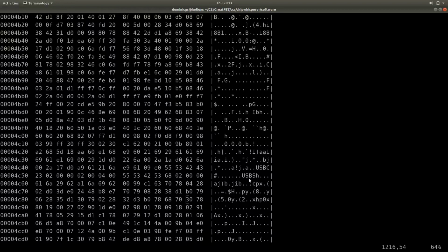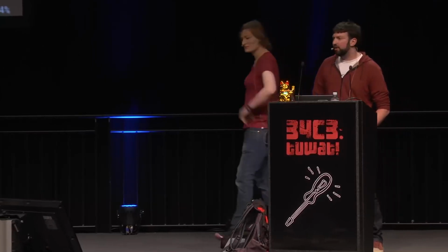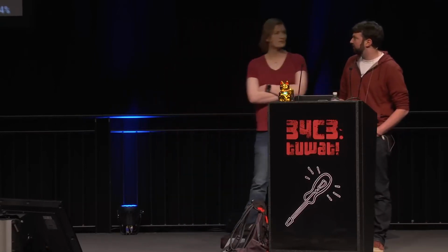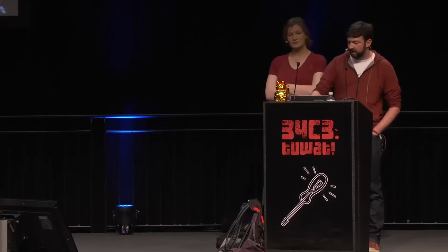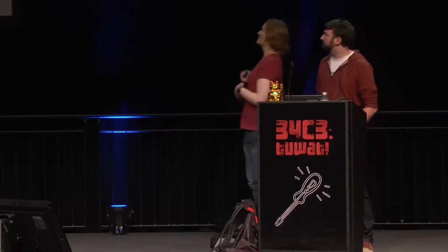So this significantly suggests that this ROM bootloader happens to have inside of it some USB mass storage functionality. And our first response was, that's weird, we didn't think this had USB mass storage. And then we went back to the datasheet and reread it, and it does. And it turns out we've dumped the code of some ROM functions that we didn't even know were in the chip. So we were able to pull out NXP's ROM code for the LPC 4300 series, and obviously you'll be able to go ahead and analyze this. And that's not particularly novel, because you could grab that out with GDB as well.